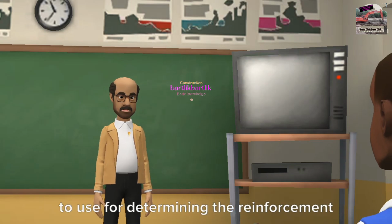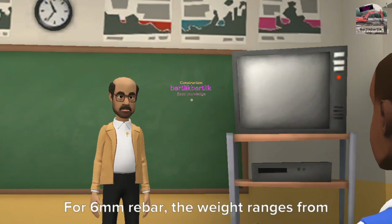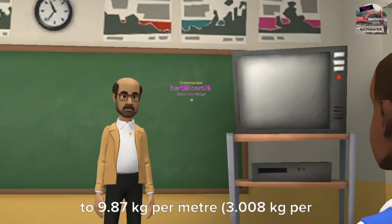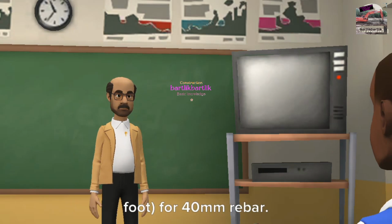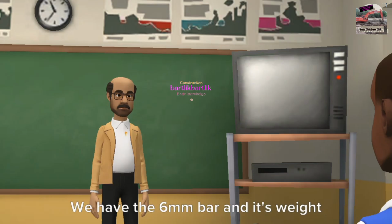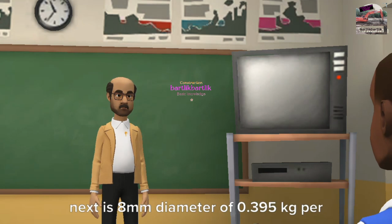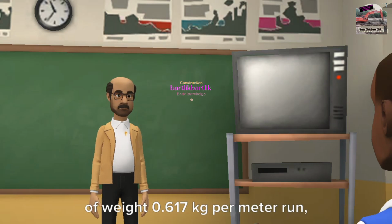For 6 mm rebar, the weight ranges from 0.222 kg per meter, 0.068 kg per foot, to 9.87 kg per meter, 3.008 kg per foot, for 40 mm rebar. What are the diameters of reinforcement bars available here? We have the 6 mm bar, and its weight in kilograms per meter run is 0.222. Next is 8 mm diameter of 0.395 kilograms per meter run. Then we have 10 mm diameter of weight 0.617 kilograms per meter run.